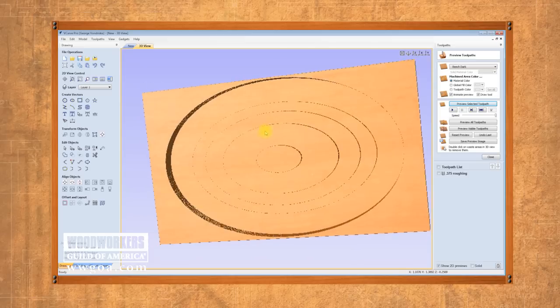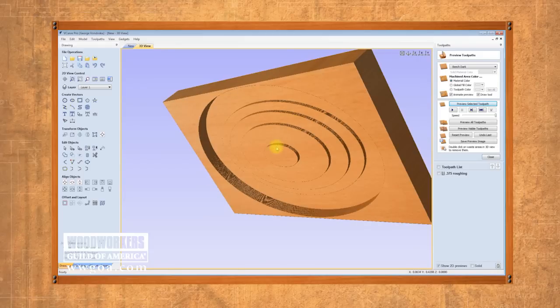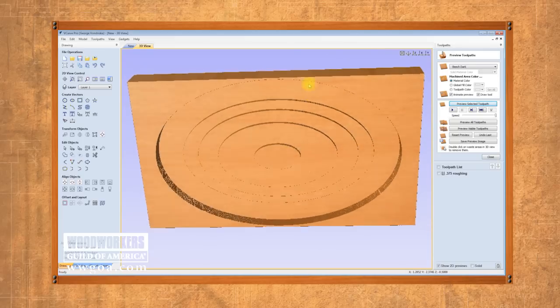Let's grab it and turn it. This is the roughing pass. See how it's left these steps kind of like a pyramid? It created that extra flat at the bottom where we're creating clearance for our V cutter. So this looks good so far.